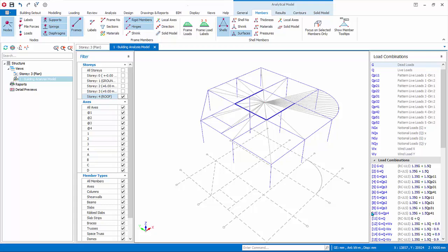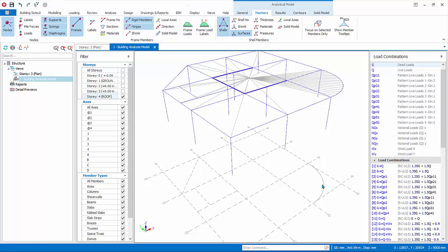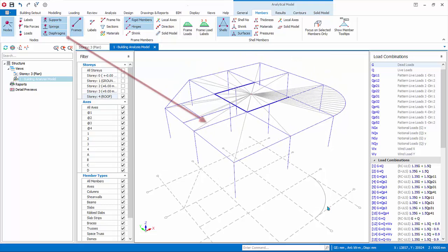The diaphragms are formed by interconnected slabs, according to the default option, slabs to define diaphragm. The gray line shows the extent of the diaphragm, joining nodes that are constrained by the diaphragm. The lines all join to the center of the diaphragm, which is also the center of mass of the story. Switch off all the diaphragms by choosing Deselect All.